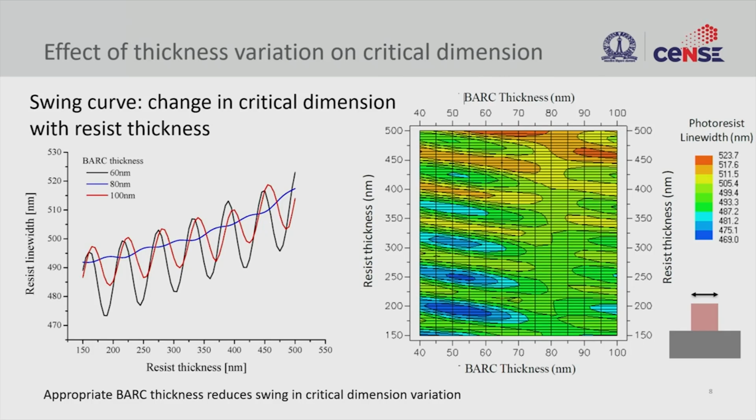Okay. So, we looked at the photoresist thickness, and then we saw this standing wave, right. So, the standing wave pattern would result in a certain CD or certain dimension, and based on the thickness of your photoresist, the standing wave wavelength or pitch will also change. Okay.